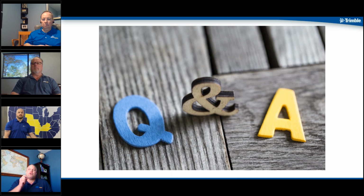These are very small things to check, but small things equal bigger things. If every time you set up the robot, you set a new control point and then you move, you're adding error with each setup that you go across the deck. If you're doing 10 or 15 setups, you're adding error every time you potentially set up and shoot new control points or add new control points in.